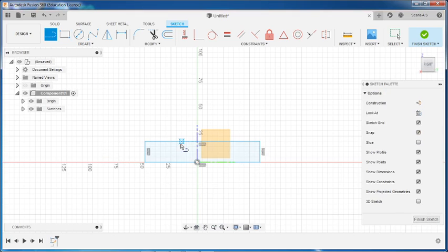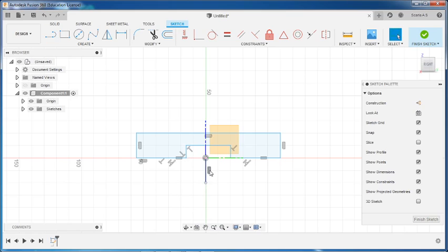then make lines here, then trim the portion, trim, then you can give equal, both of these are equal. Then we will draw a small center line for making symmetry. Select this line and press X, click onto the screen. Then you can give symmetry.